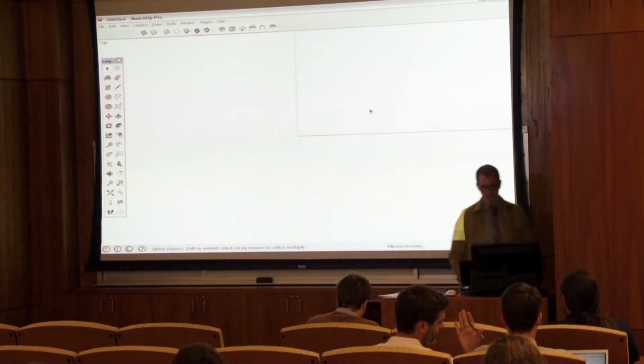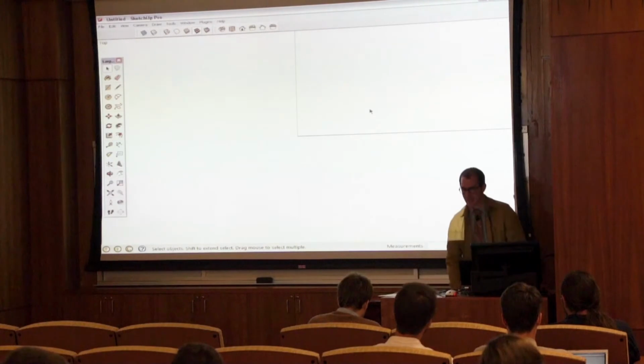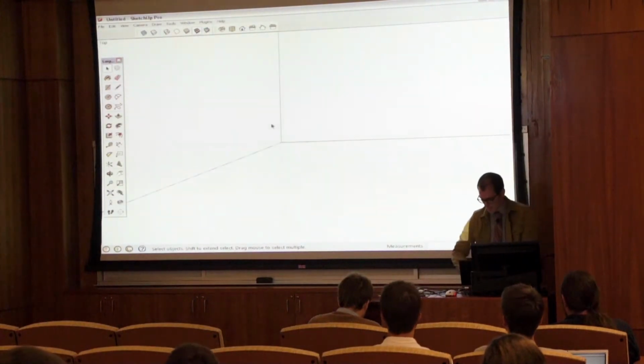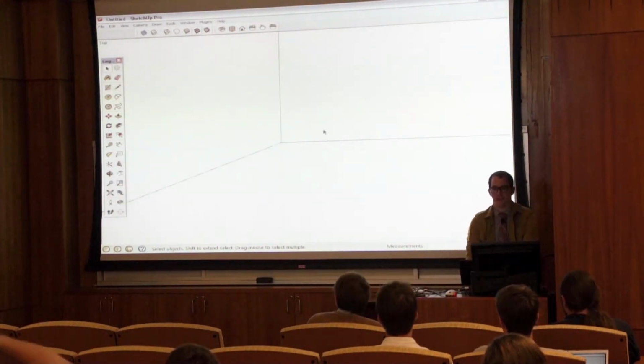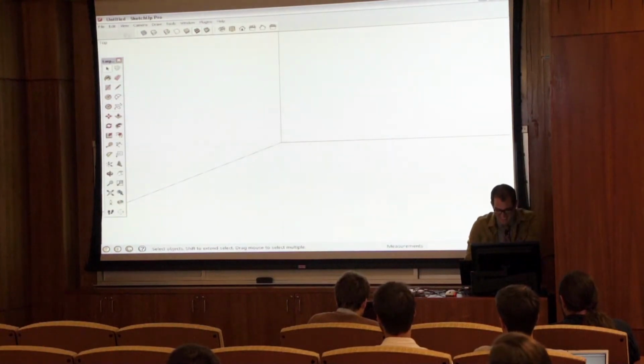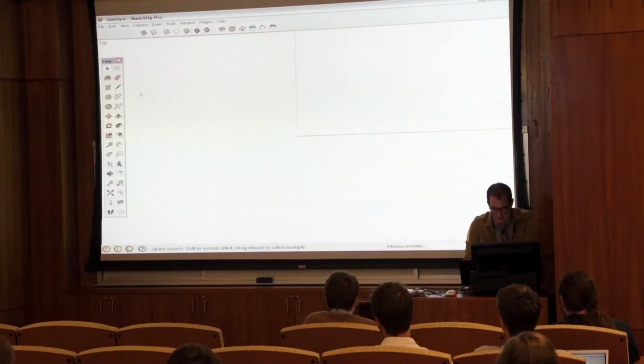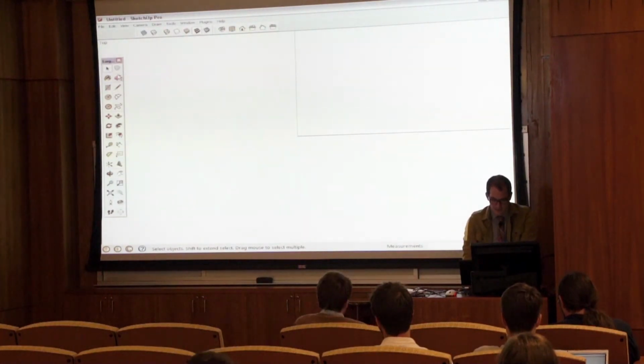All right, so let's go ahead and start with the drawing tools. I'm going to break down first just a large tool set. To break down the large tool set, you basically have your line tool, paint bucket tool, eraser. These 6 are your drawing tools: circle, polygon, line, freehand, arc. Then you have your modification tools like push, pull, offset, follow, scale, rotate, move.